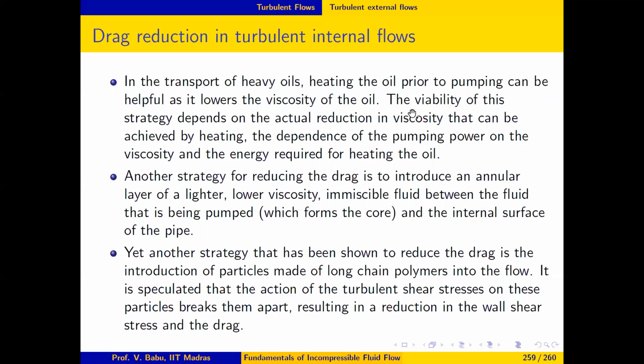Now, of course, we have to spend energy to heat the oil. So the economic viability of this strategy depends on how much reduction in viscosity we can achieve by heating, and the reduction in pumping power as a result of this reduction in viscosity when compared against the energy that is required for heating the oil. So there is a cost and a benefit associated with this strategy. The cost is the energy spent to heat. The benefit is the reduction in pumping power due to the reduced viscosity. So we need to balance the cost against the benefit and then try to determine an optimum temperature to which the oil should be heated so that we enjoy an overall benefit in terms of pumping power.